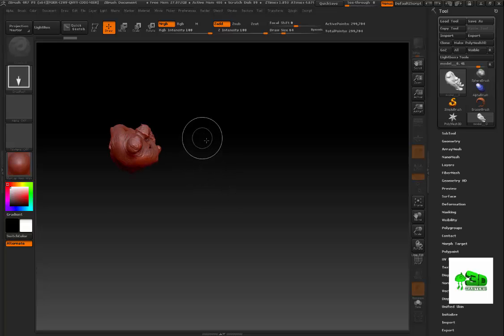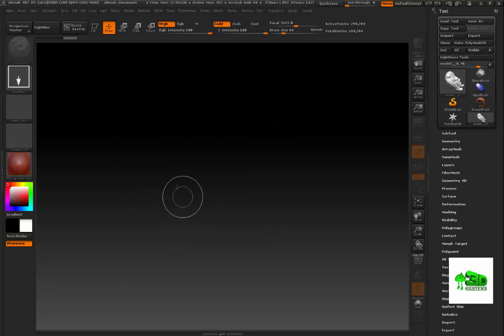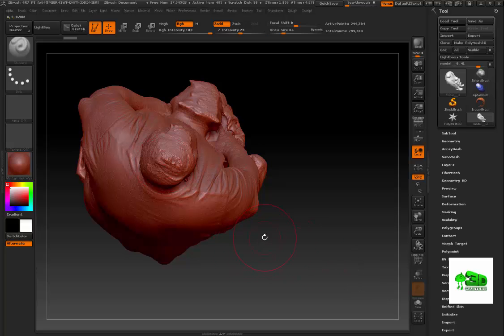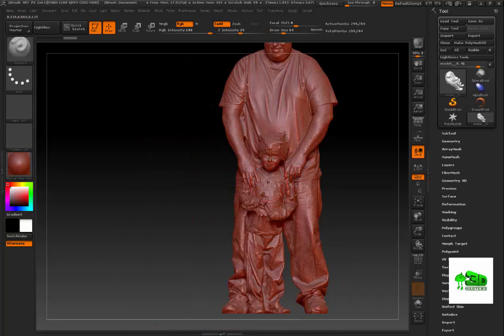And I go, uh-oh. Oh, no. Then I got, oh, shoot, now I got too many of them going in there. Well, guess what? That's a normal path that everybody follows when they start using ZBrush. What I'm going to do is hit Control-N, get rid of them, and redraw one more again, and then hit T to bring it in there. That will get you back out of that problem. That's the most common thing I see with everybody using this.